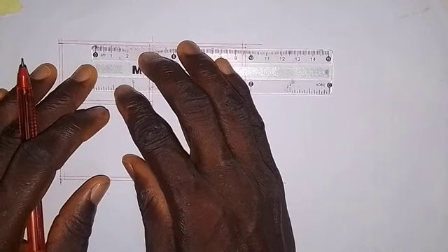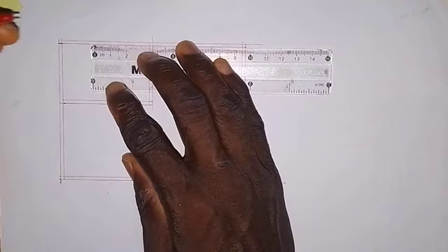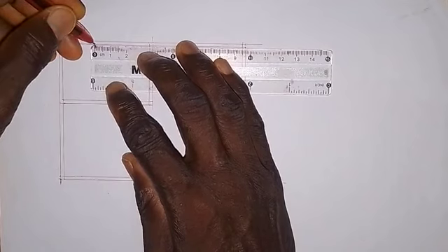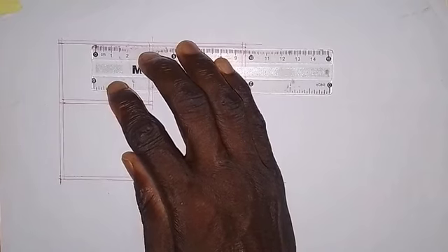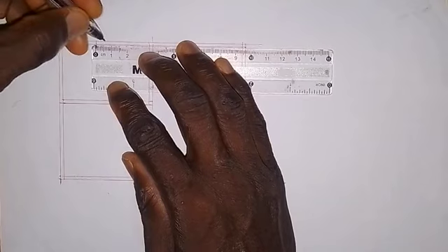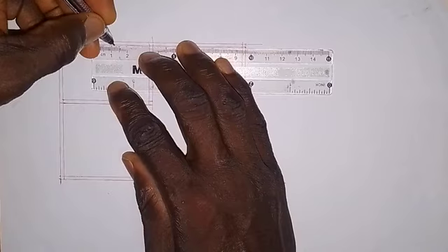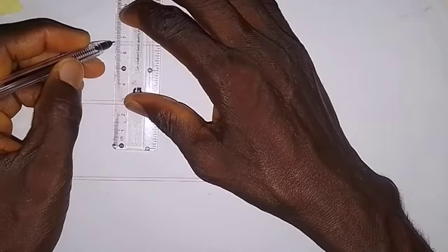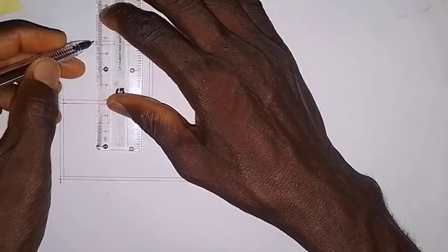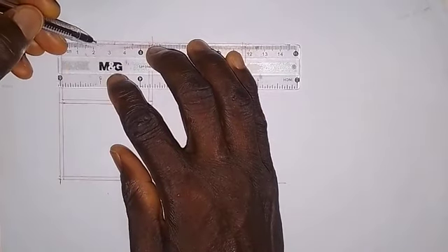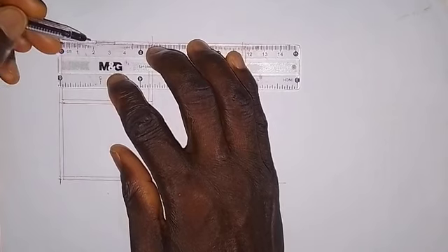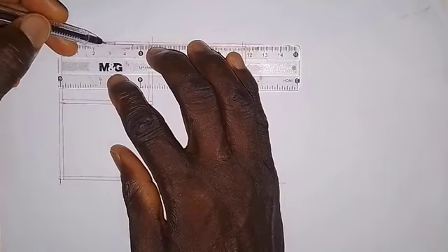For me, this should be the midpoint of this wall, around here. So you put a mark here, at 0. Then you take 12 millimeters up. So this is 12 millimeters. Here you draw a line within this wall, like this. Then draw 2 straight lines within this space. Just draw like this within this space. Come in a bit and draw another line like this. So we have fixed this window.